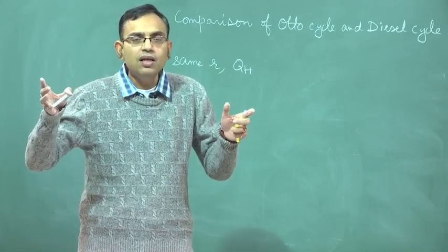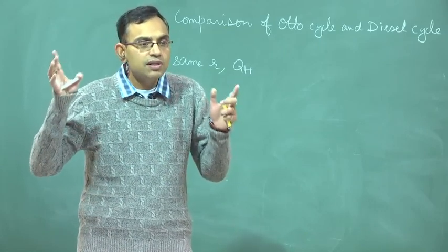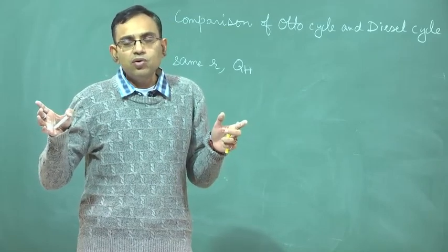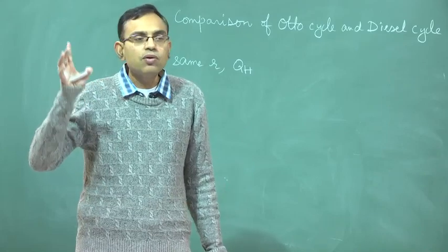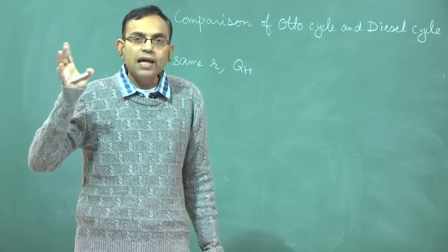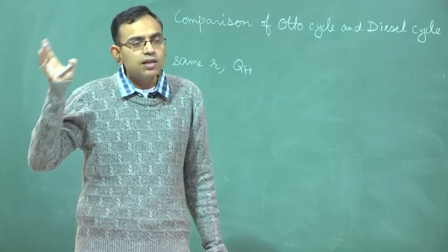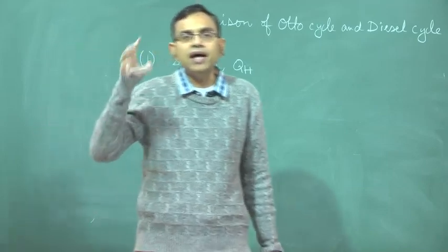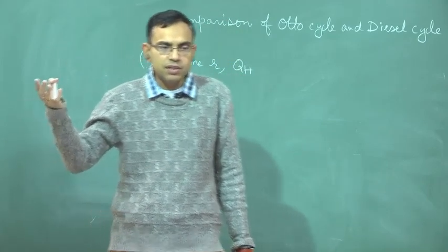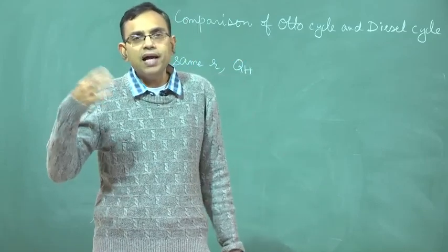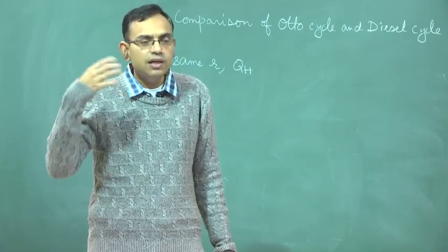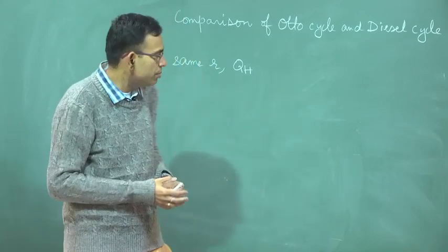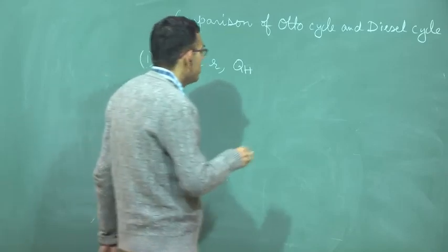All these things are equal if it is an internally reversible cycle, because if it is not an internally reversible cycle you cannot write del Q equal to TdS. So, area under the TS diagram is equal to cyclic integral of del Q, that you can write only for an internally reversible cycle. Similarly, area under the PV diagram is same as the net work done for an internally reversible or quasi equilibrium process or a collection of quasi equilibrium processes. So, these things we must remember.